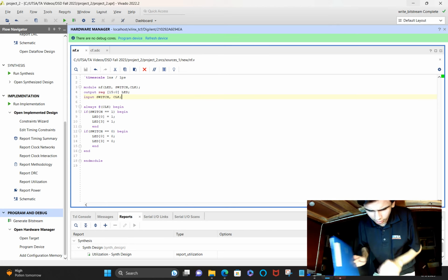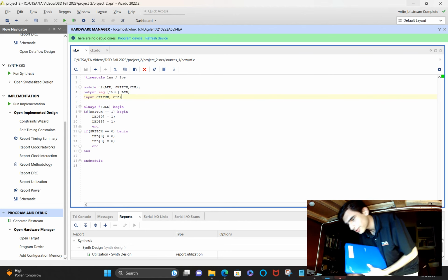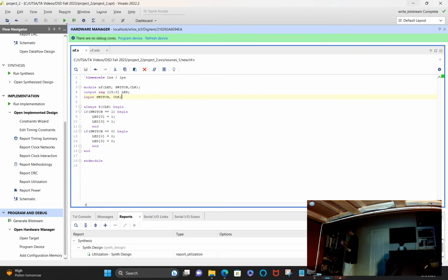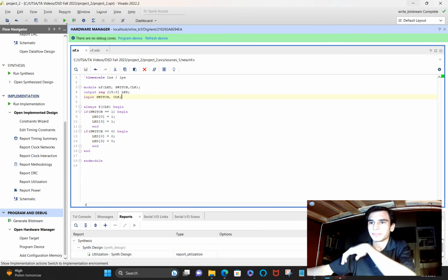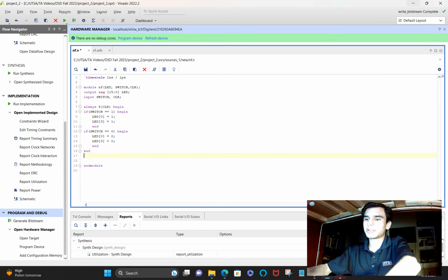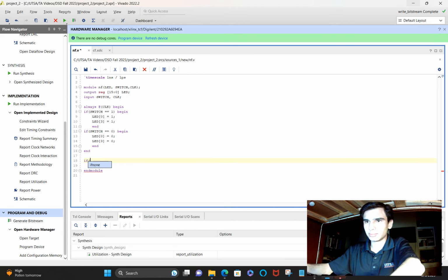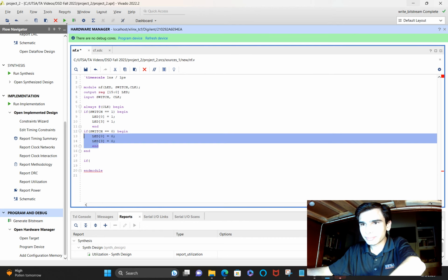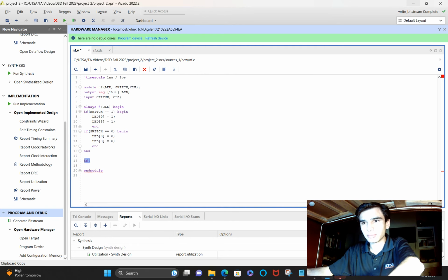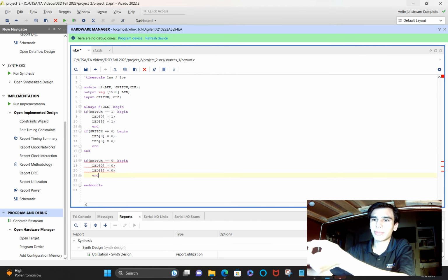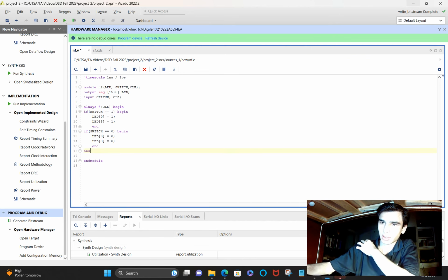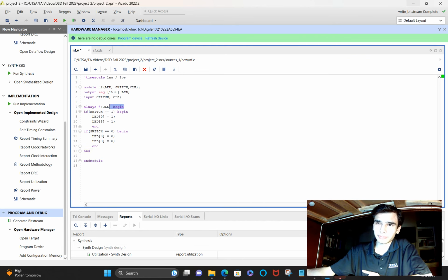I don't know, I can't find it. I guess it'll be a little bit of a mystery. Okay, I'm pretty sure you can't. It doesn't have to be a mystery. Let's just see what happens. Pretty sure you cannot put an if statement out there. Yeah, there it is. So yeah, an if statement can only go in an always block.